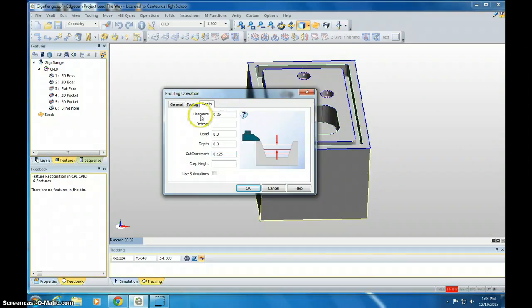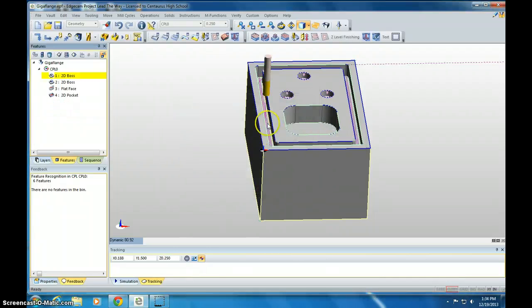So you may need to rewatch that to see it. I've also copied all of this information onto that Google Doc for reference if you want to see them all printed out there quickly. So we click OK, and you can see that 1/8 inch tool comes in here. The groove is exactly an 1/8 inch, so that cuts it perfect. That's the reason why we chose that tool.